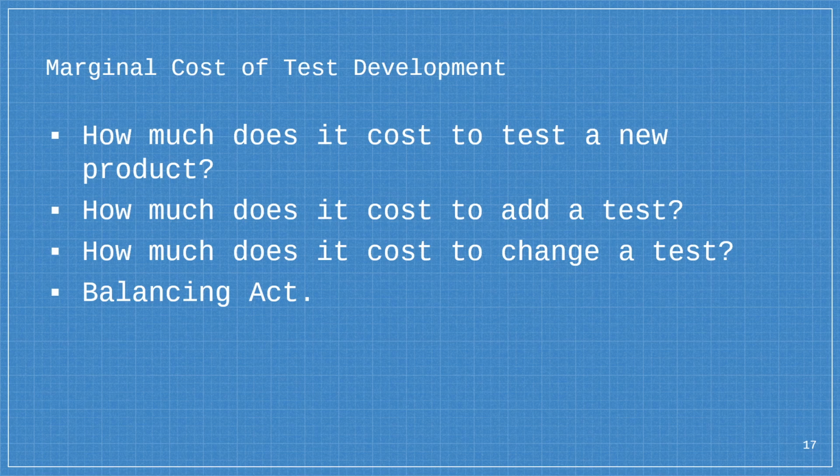You probably don't want to put on a switch matrix, and then have an operator hook it up manually like that, or hook it to some sort of fixture. But if you do it that way, then you have a lot of flexibility on how you can hook up to the tester, versus if you just have a pin field, then you have a lot more flexibility in how you can build the fixtures, but a lot less flexibility in how you hook a unit up to it.